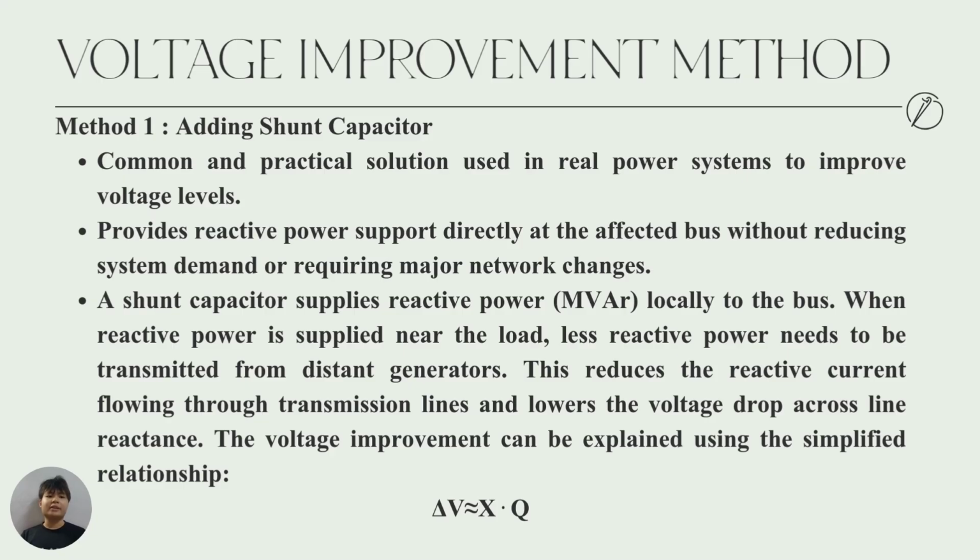So because it's a common and practical solution used in real power systems to improve the voltage level, and it provides reactive power support directly at the affected bus without reducing system demand or requiring major network changes. So a shunt capacitor supplies reactive power locally to the bus.